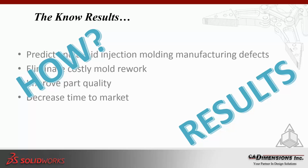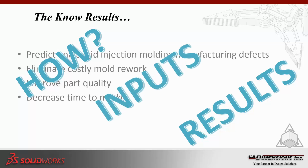How will my part fill? Are there any air traps? Are there any weld lines, knit lines? Are there any voids? Those are the types of results I'm talking about. And these results are highly driven by inputs, your inputs into the software.